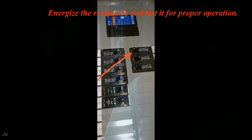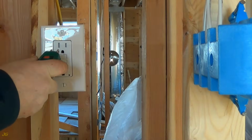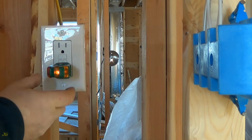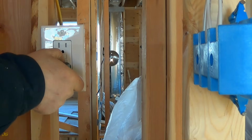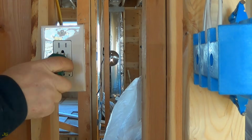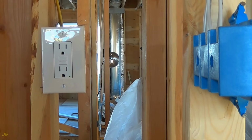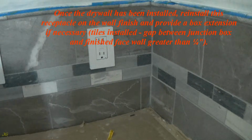Energize the receptacle and test it for proper operation. Once the drywall has been installed, reinstall this receptacle on the wall finish and provide a box extension if necessary. Tiles installed, gap between junction box and finished face wall greater than 1/4 inch.